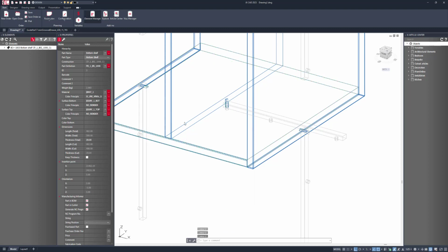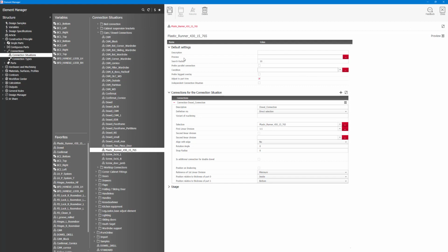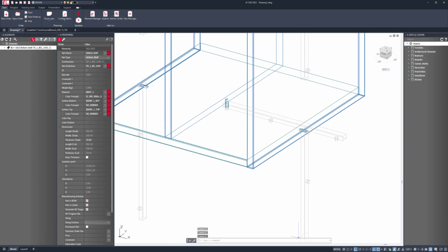So into Element Manager, and this is where rather than going in and out of Element Manager, we should always use Organizer, because by having Organizer open and off screen, we can quickly make the changes, refresh the data, and that will then update the model, and then we're not constantly going in and out of Element Manager via CAD. So if we go into Element Manager here, I want to then go back to the connector set. So let's go to hardware, and this is just happening off screen here, but it'll give you a chance to see the live updates so that I can get these positioned as we go through. So I'm just going to click on the fitting, and then in here I'll just want to get rid of my second subassembly.